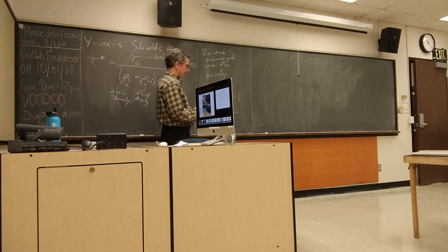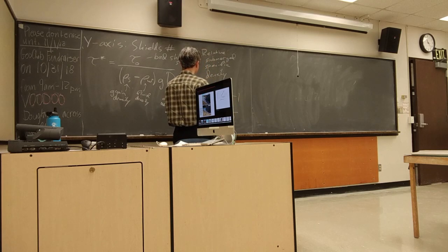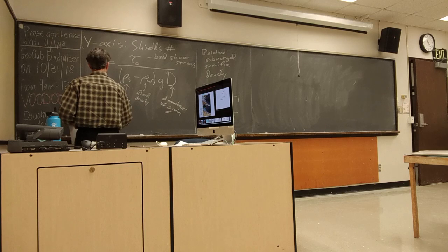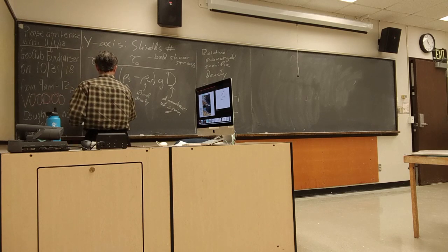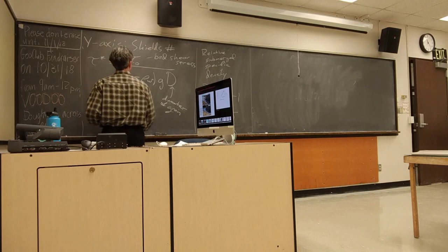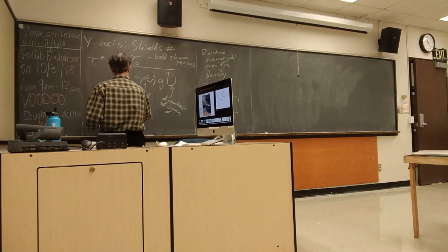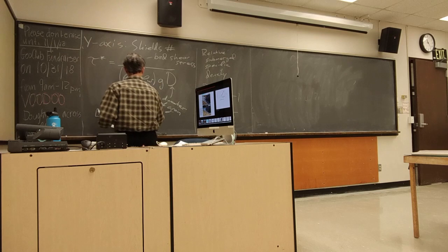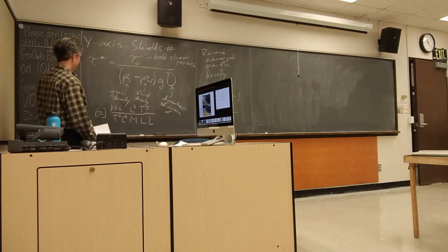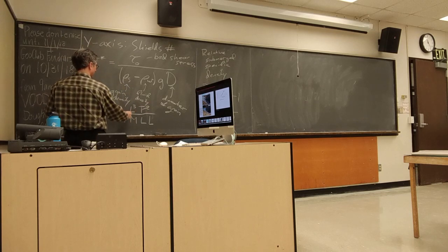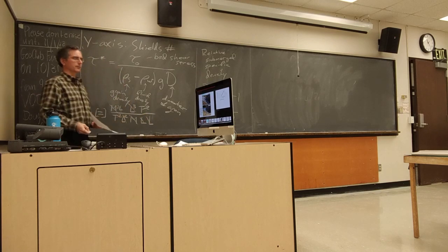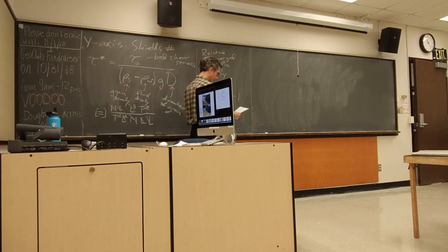All right. In order to make it simpler still, oh, you know what though? Always a good idea to check our units. Let's just make sure this is indeed unitless. So, let's see, kilogram meters per second squared per length squared. Density and mass down here, volume there. Gravity, length per time squared, and length. Okay, I got t squareds cancel. L to the fourth, so all my L's cancel, my mass cancels. Yes, indeed, it is dimensionless, if you were in any doubt. Okay.